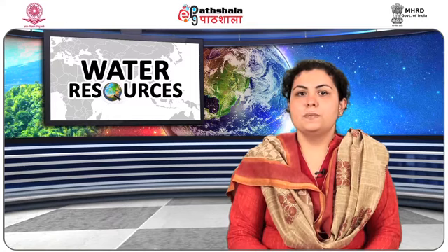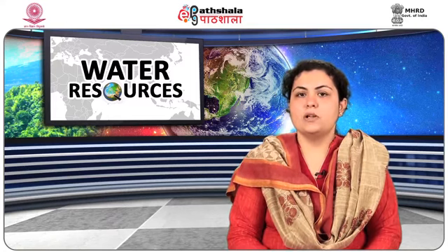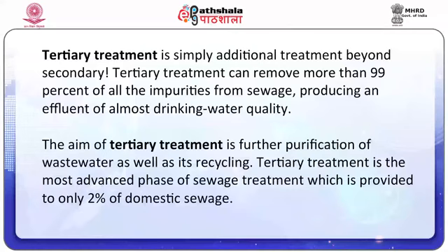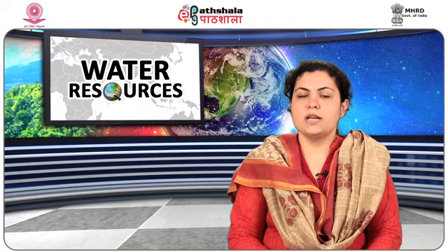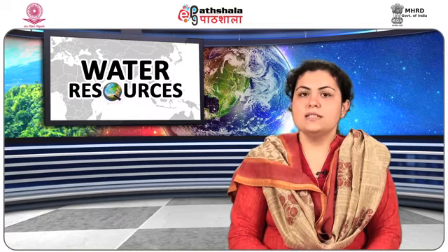An example of a typical tertiary treatment process is the modification of a conventional secondary treatment plant to remove additional phosphorus and nitrogen. The aim of tertiary treatment is additional purification of wastewater as well as its reuse. Tertiary treatment is the most advanced phase of sewage treatment, which is provided to only 2% of domestic sewage. The main function of tertiary treatment is to decrease the load of nitrogen and phosphorus compounds present in the effluents